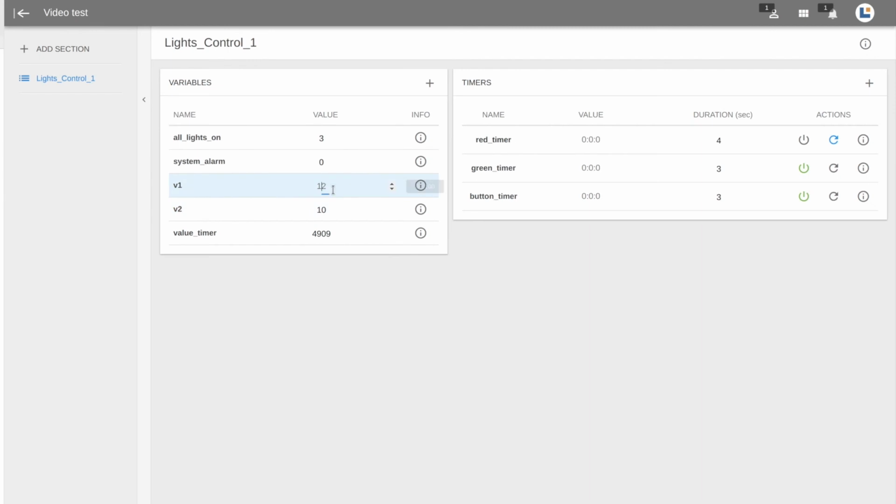Now if we go back to function and let's say we put this to 0, everything gets reset, everything's fine. We go more than 10. It's going to wait 2 seconds this time, and after 2 seconds, that alarm gets activated. So there might be situations where a value goes over a certain limit, and you want to wait a little bit to send an alarm out. You can just wait a certain amount of milliseconds, and then if that persists for more than that time, you can then activate your alarm.